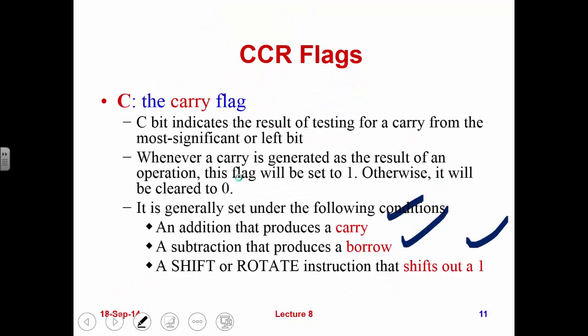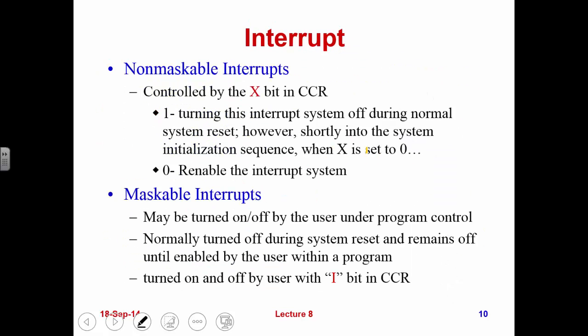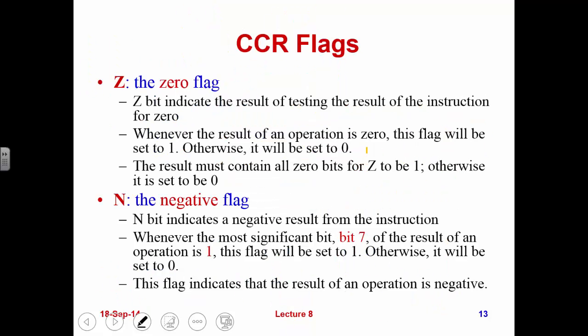Next bit here is flag bit Z. This one I think is pretty easy. That means if the previous operation produces a result of 0, that's going to make this flag bit 1. Otherwise, it's 0. Or in other words, when you do subtraction between 2 numbers, if these 2 numbers are absolutely the same, our result should be 0.